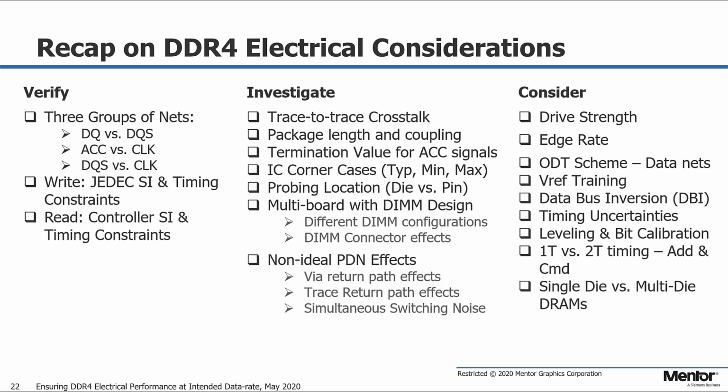Just to recap, I explained using this table that there are many JEDEC requirements, layout, and device electrical effects that you need to include to verify that you have plenty of margins. You will want to do this before fab out by simulating. If you have plenty of margins in simulation, which idealizes some of the effects such as the PDN and return path effects without the power aware simulation, then you can be confident that at least you will have enough margins in the lab.